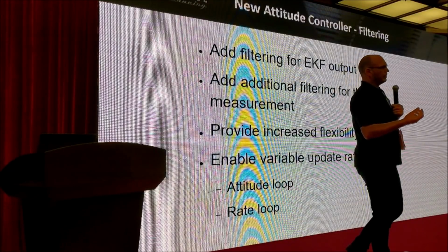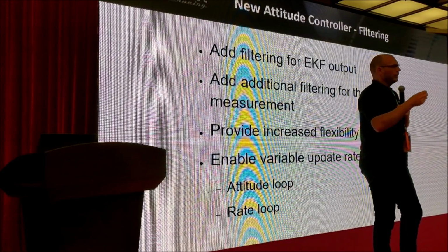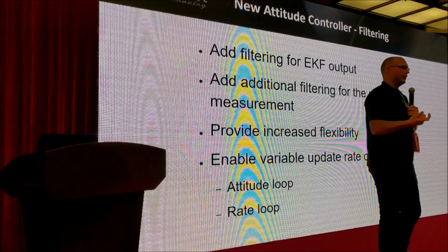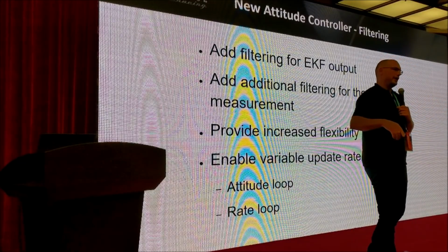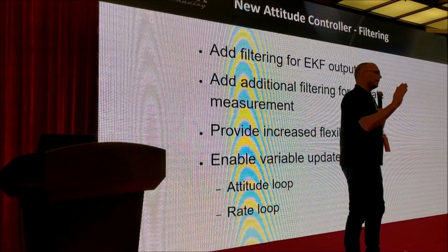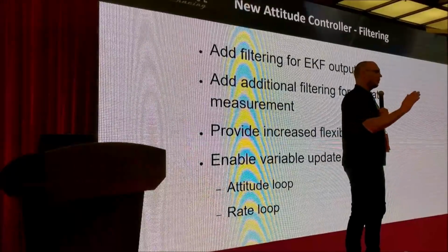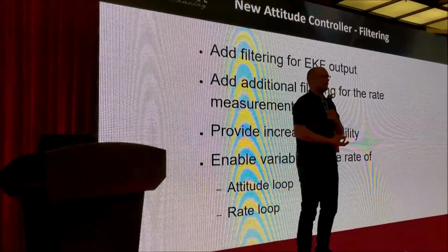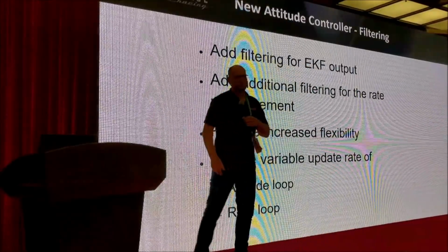We're also looking at providing a function that can automatically tune that notch filter up and down based on an FFT that's running in the background, so that it can track that if you know what type of noise, like blade passage frequency, that could be very useful.